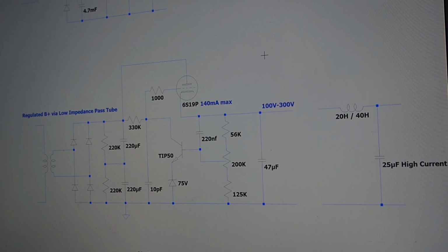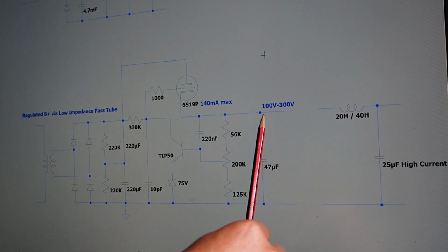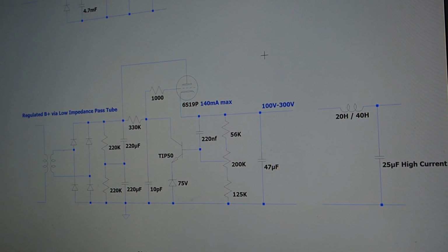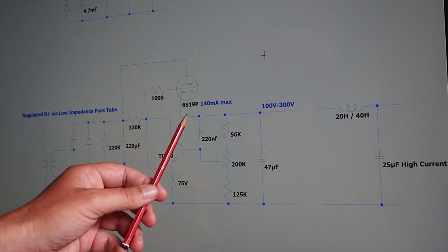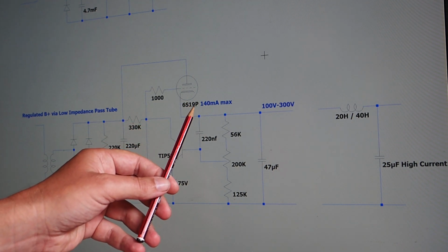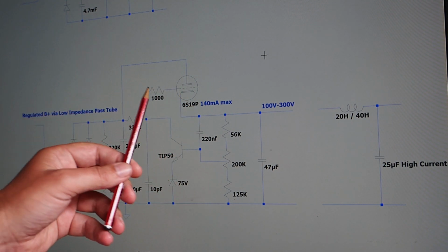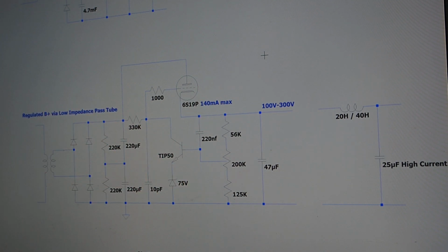Now let's look at the limits. What you have to realize is what people generally want with a power supply is a very low impedance power supply. Now when you make it active like this, it appears to be a low impedance circuitry if you measure it with some measuring standards. But of course we have a plate resistance here. Now this tube that I employ has 400 ohms. If you parallel, it's 200 ohms, so that's pretty good.